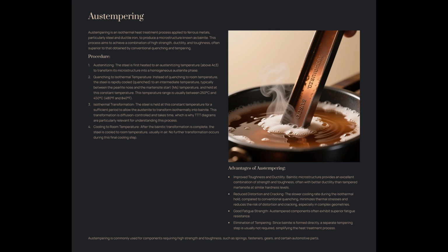Good fatigue strength. Austempered components often exhibit superior fatigue resistance. Elimination of tempering. Since bainite is formed directly, a separate tempering step is usually not required, simplifying the heat treatment process. Applications. Austempering is commonly used for components requiring high strength and toughness, such as springs, fasteners, gears, and certain automotive parts.